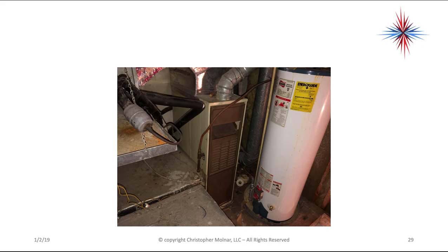Now, the reality. Okay, this is a 1988 system. They're probably going to replace it. They need totally new ductwork when they do. So airflow problems you can find on just about every system. It's an evaluation of how much they are affecting performance. In this system, the airflow was half of what it was supposed to be. And over the years, the charge of the refrigerant actually had been adjusted to account for the lower airflow.